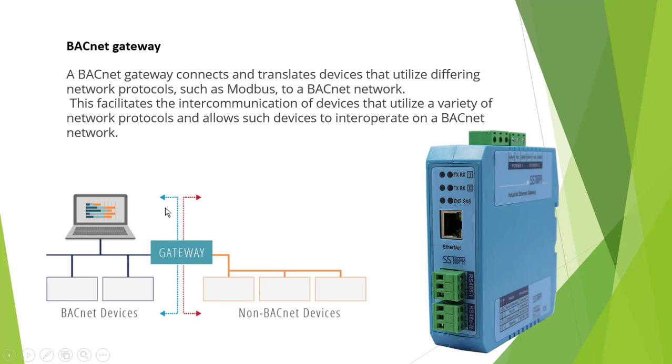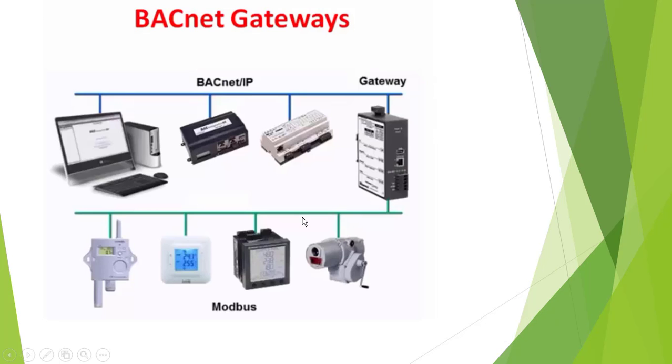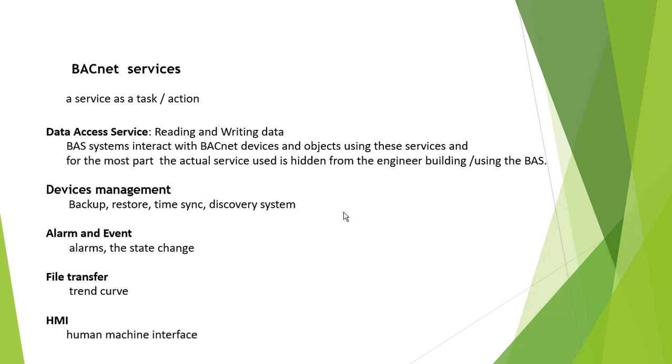Same thing is OPC service. Sometimes we communicate using the gateway. This gateway is RS485 communication. Look like this. This is the BACnet gateway. A BACnet gateway uses BACnet IP and Modbus communication through the gateway. BACnet service.